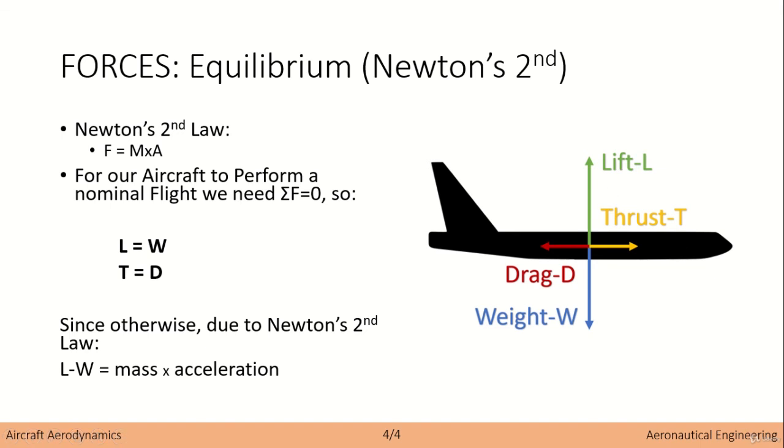In addition, when the thrust operates, you start to have a velocity of the aircraft, and therefore the lift starts to grow. And as you can imagine, it is when we have a certain velocity that the lift is equal to the weight. In that case, the aircraft is in momentary equilibrium.